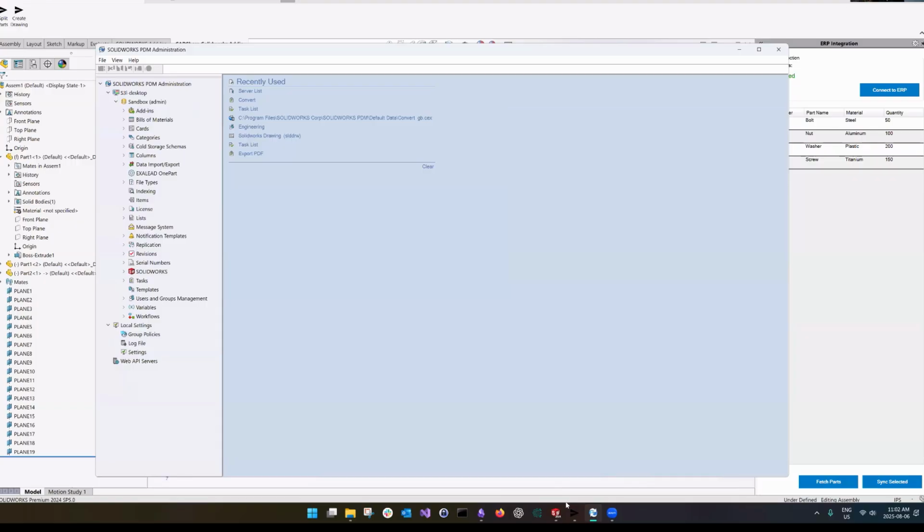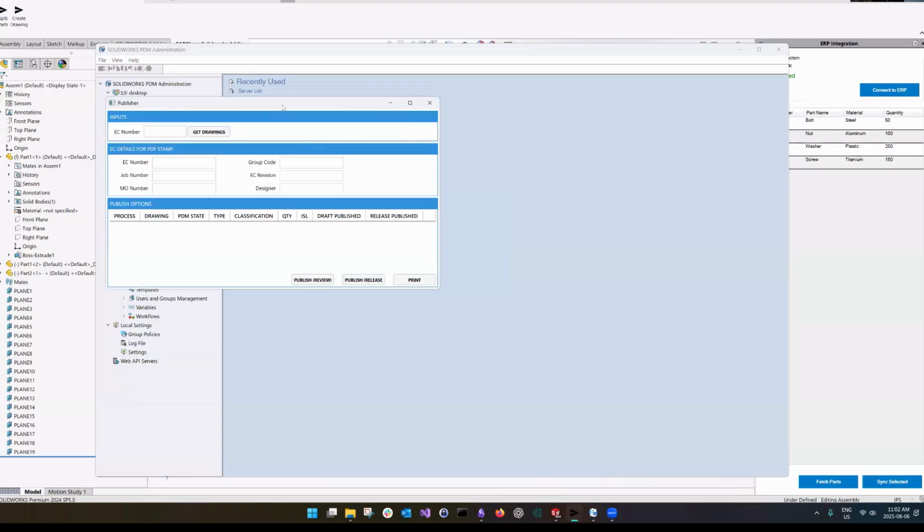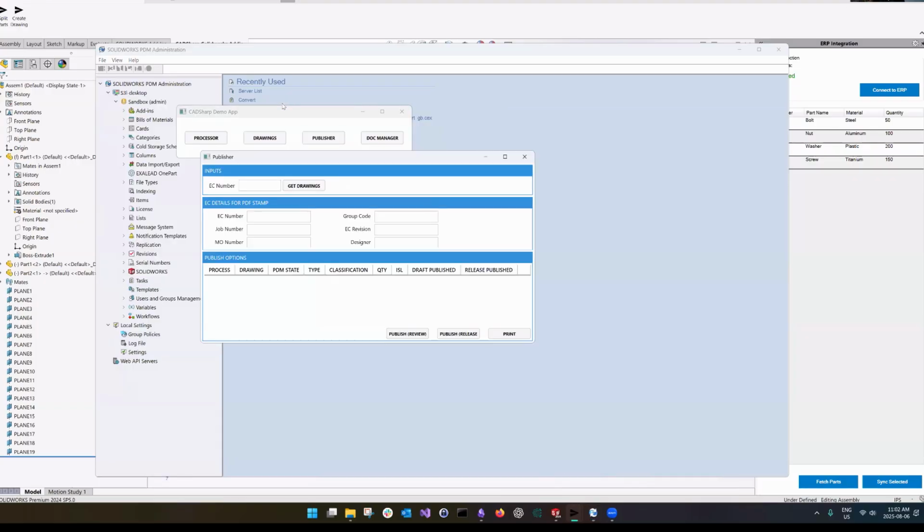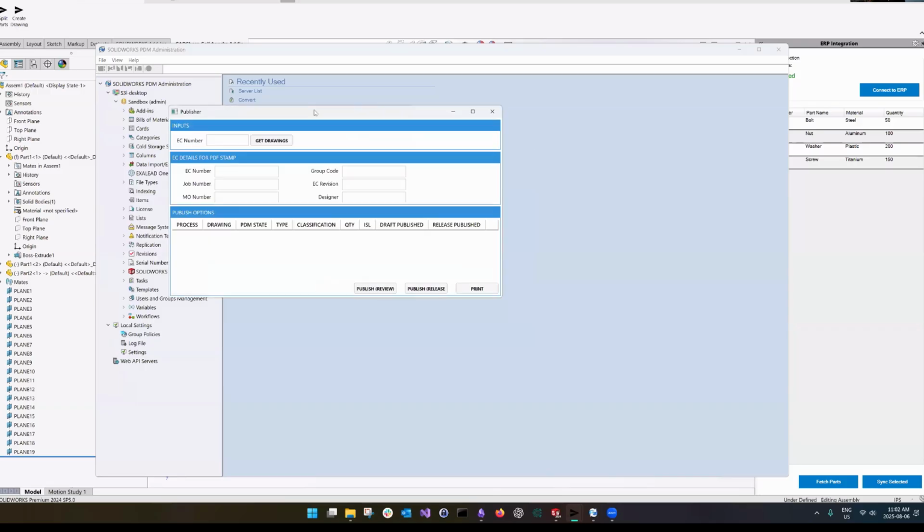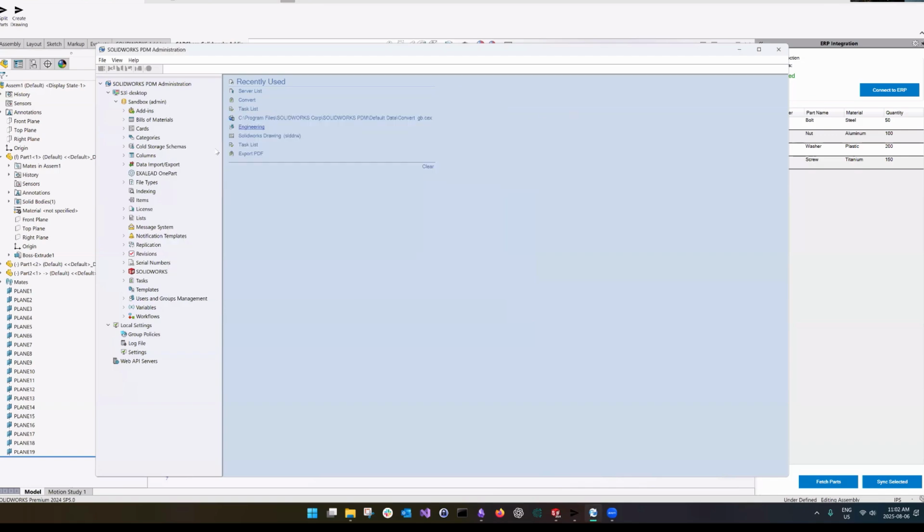So for example here, something like this would probably have a settings interface where you would specify which PDM vault to use, and then it will log in with the active user, and we can read and write values to the database. So that's a standalone app that uses the PDM API, but add-ins themselves can modify PDM's functionality directly. So something we do a lot is called a task add-in.